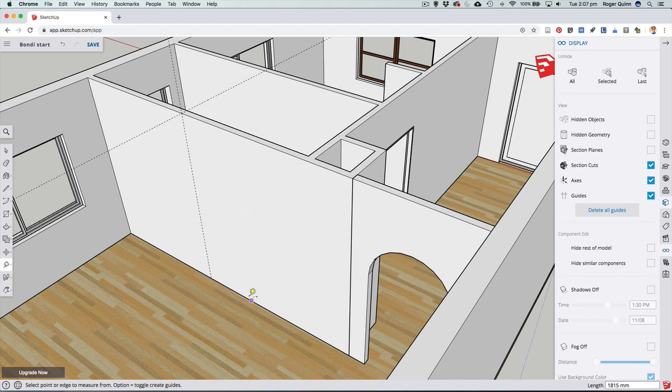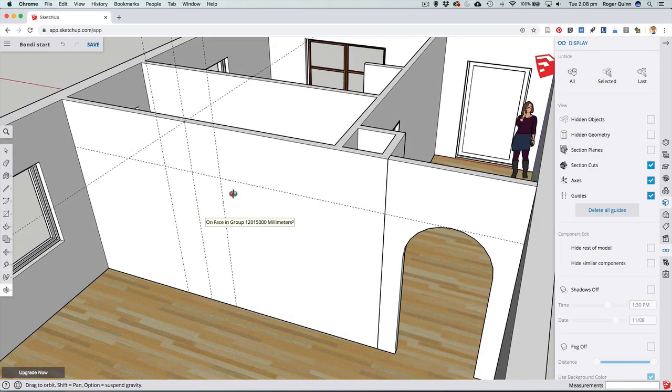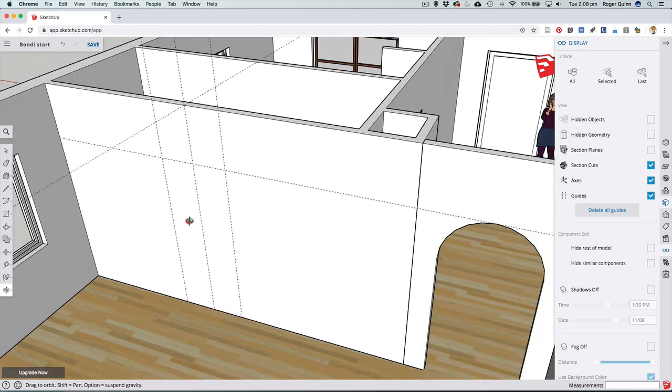Now, a good standard door height is 2040, so there's my door height. The standard single door width is, say, 820. They do vary, of course, but I'm using that to be consistent across this model. I'm going to go 820 / 2 because I'm trying to build this off the center line, which gives me 820 across there. Now I can knock my hole in there.